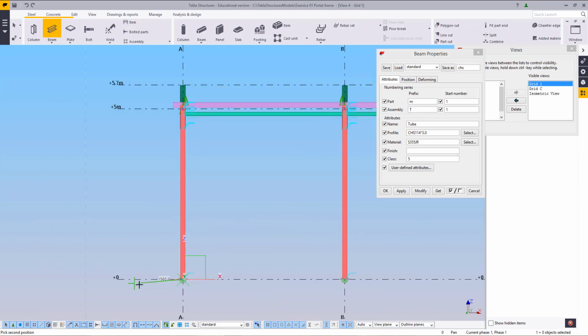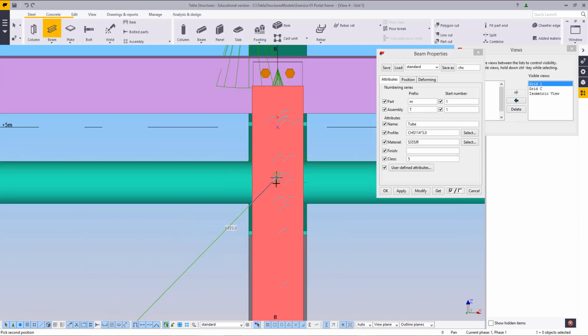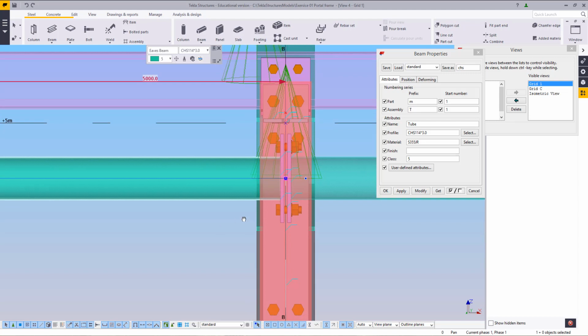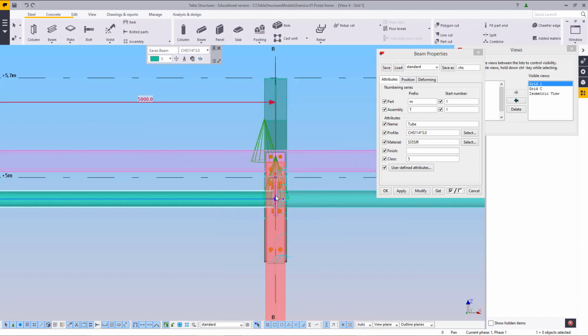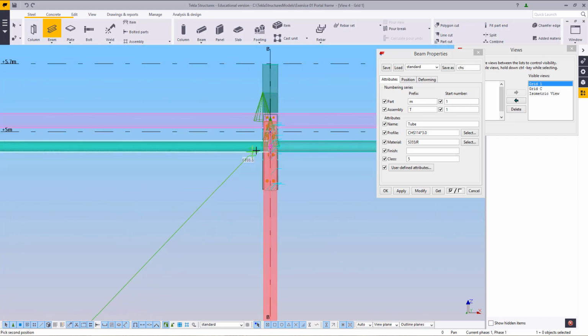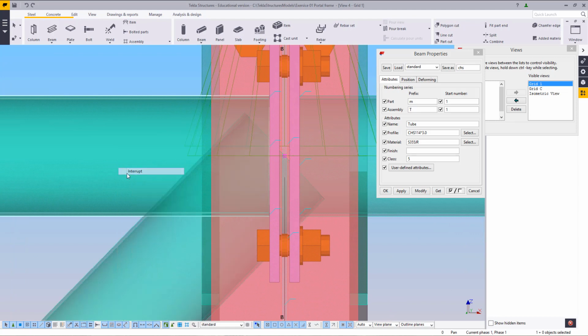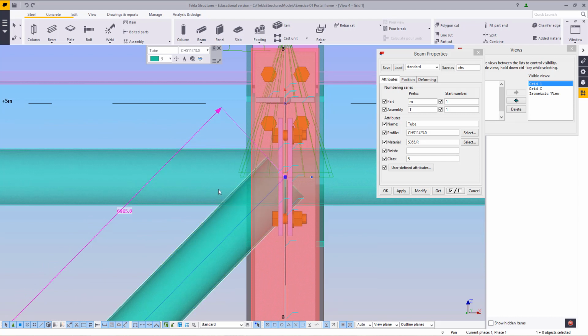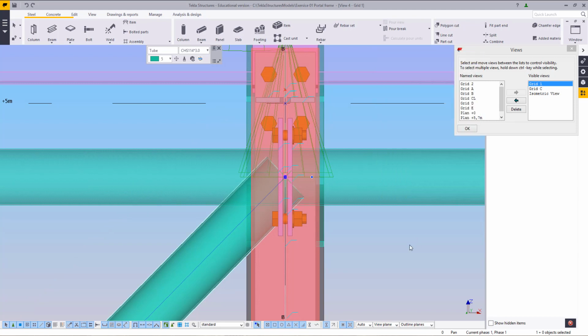Starting from the bottom on the outside, heading in to somewhere over here. Let's just use Control to see through everything. And that doesn't seem to be a point. So select your eaves beam. This gives us a nice little point to work from. Start from the bottom and we put it on over to that point. And this will ensure that our bracing is directly onto the eaves center. Let's close this up.